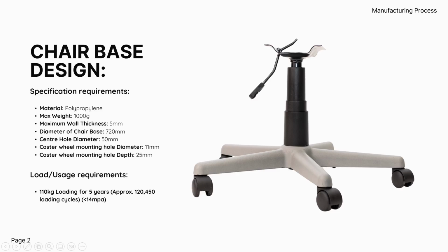So what does that mean? That means that you have 5 chair base, right? 5 chair base. So chair legs, I mean. So 110 kg is 1100 newtons of force. We just use 10 newtons per kilogram in this case, because F equals ma, right? And you need to divide the force by 5, right? So each leg is going to handle 220 newtons of force, right? Not 1010, right? Okay, so you need to understand that, right?